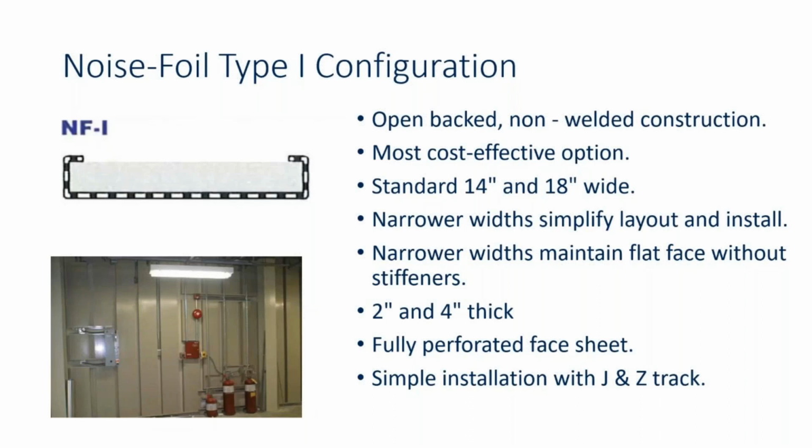Narrower widths will simplify the layout and installation and maintain a flatter face without the need for internal stiffeners. However, narrower widths will also mean that there'll be more numerous panels for the same surface area of coverage, which means that the installation may take a little bit longer.